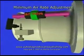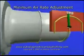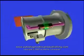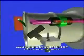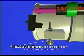Adjusting the minimum air rate entails synchronizing the throttle plate adjustment screw, closing the IAC valve, and readjusting the TPS. By properly adjusting the point at which the throttle plate screw touches the throttle lever, we can prevent all kinds of idle speed problems from happening.